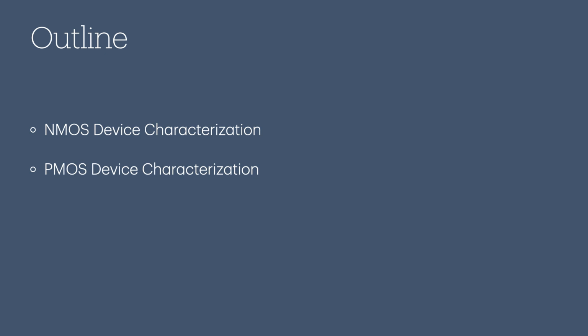For this session, we're using LTspice. It's free and easy to find online. Our focus is a 45 nanometer process node, but don't worry too much about that detail. This method works for any process node and with any simulator, whether you're using LTspice, Cadence Virtuoso, or others. The most important thing is to grasp the method, not just the particular tools. We will start characterizing the N-channel MOSFET.